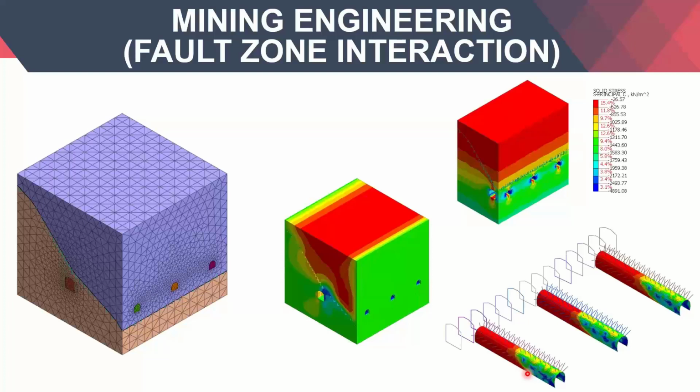So people among you who have been to deep underground mines will be able to see this effect right through the eyes. I have also experienced and seen these things, like when the stresses along the transition zone became so high that the rock bolts completely yielded, and then the shotcrete and the wire mesh was completely folded. So these do happen in deep underground mines.